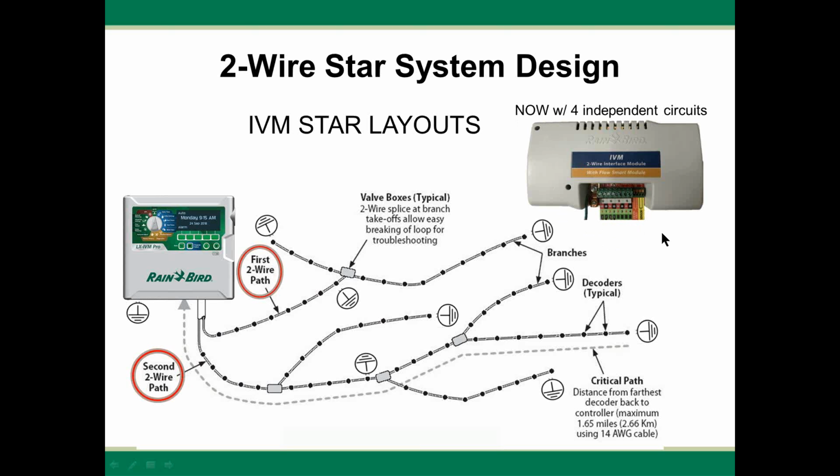Though we've had 4 outputs with our LXD controllers in the past, all 4 of those outputs are the same electrical circuit. This holds true for all of our competitors, as the output modules for all of these tend to be exactly the same circuit, same electrical component. What happens is when somebody cuts that 2-wire path or a short is detected, unfortunately that over current draw, because there's a short on that 2-wire path, now shuts down the entire controller. I think we've all experienced that in the past, and those are never fun to experience.